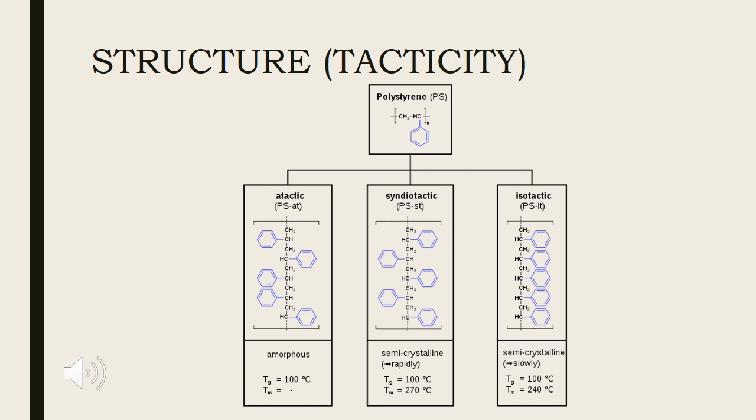In polystyrene, tacticity describes the extent to which the phenyl group is uniformly aligned in the polymer chain. Tacticity has a strong effect on the properties of plastic. Standard polystyrene is atactic. The diastereomer, where all the phenyl groups are on the same side, is called isotactic polystyrene, and is not produced commercially.